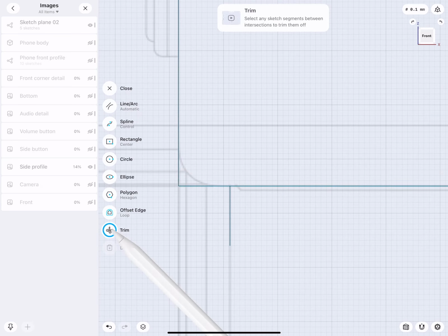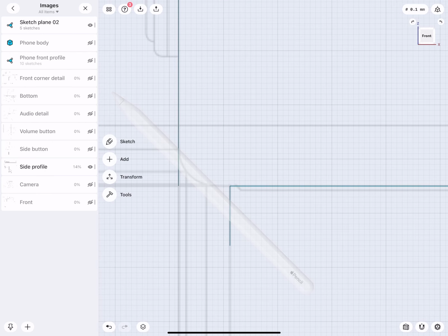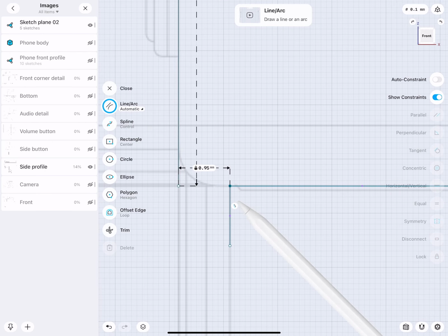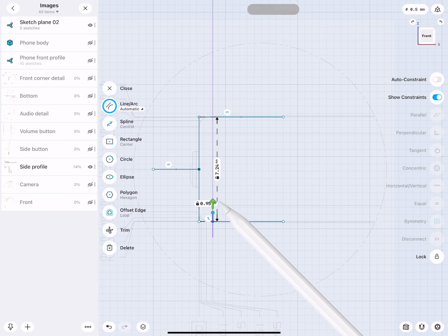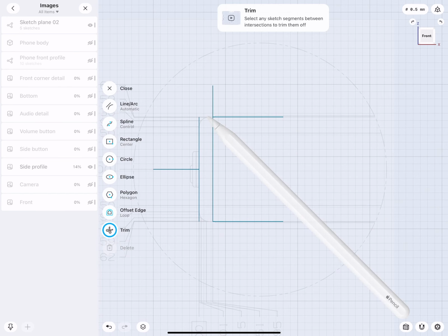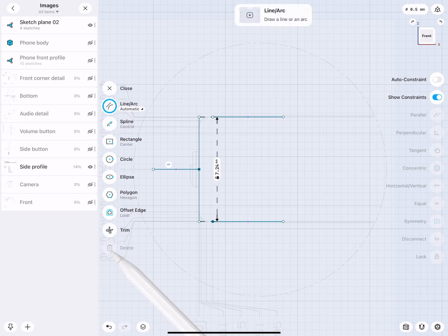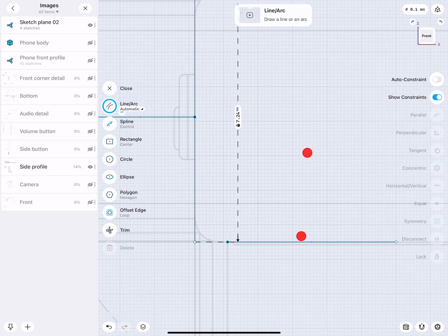Because in there I can trim this. This point for the moment I lock. So I can select this point, simply move this up and then trim it there. And this line now I can delete. Also here we lock this, very good. So you see how quickly I just found this one corner point.